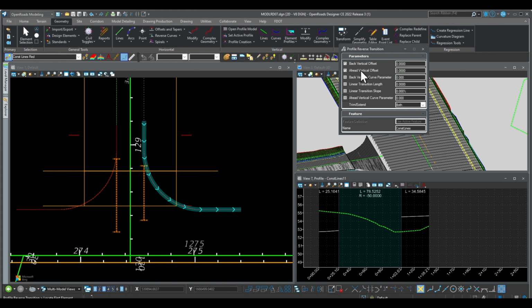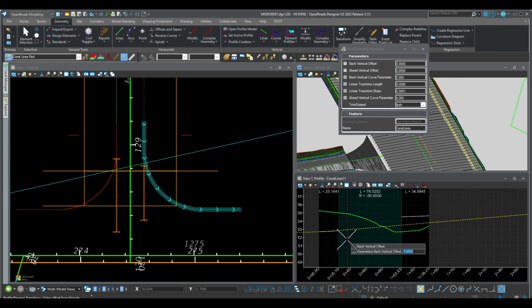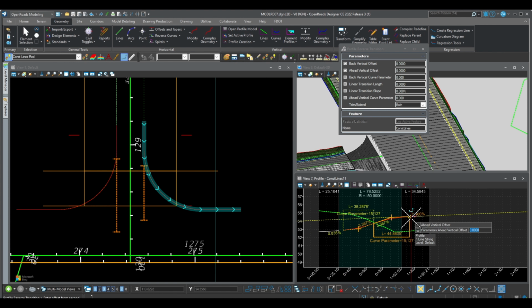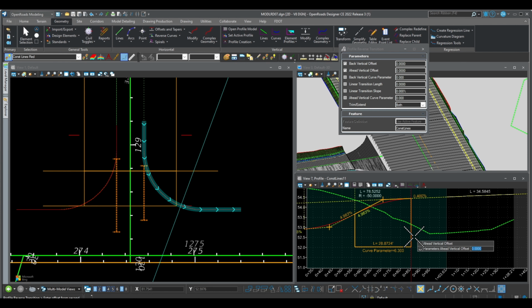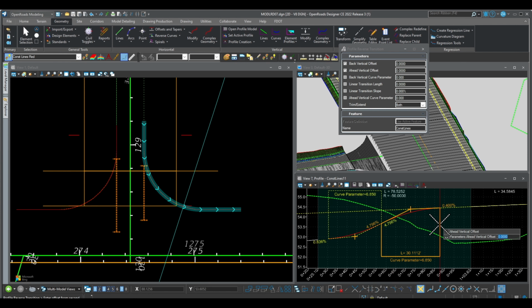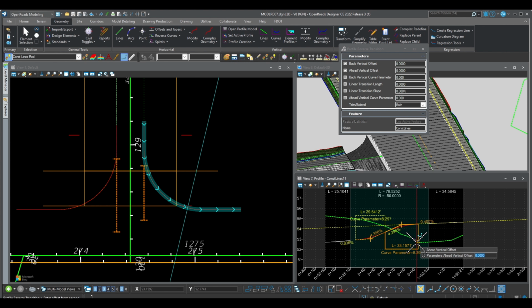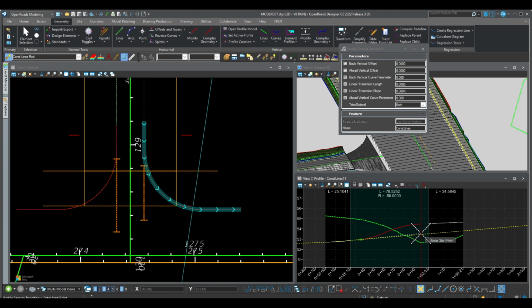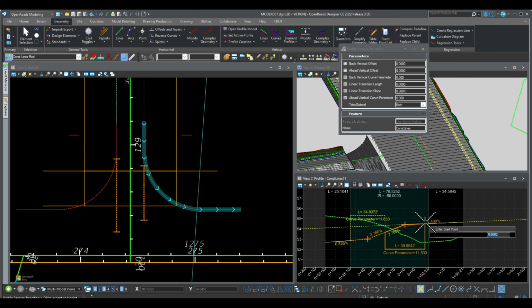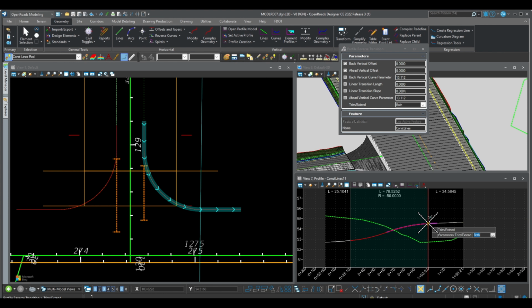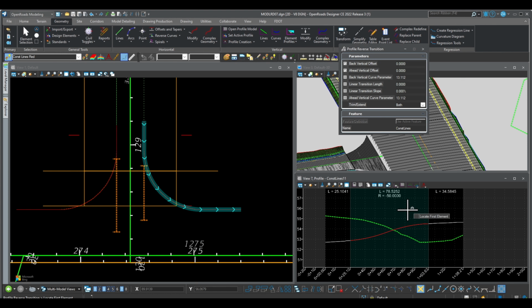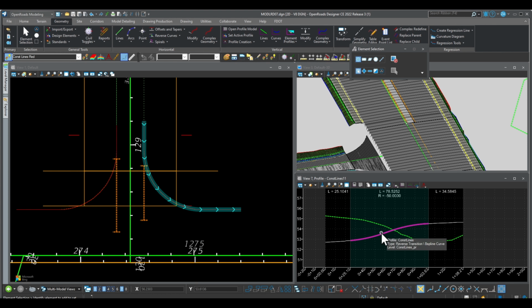So let's select the first element, which is this one. And then just click anywhere, because I already locked it on 0. It's not going to go any vertical. And then let's select the second element. And you see here right now, we have something. It's like it's showing us something, right? So let's just click on 0. And then let's go to start, where I want to start from here, and I want it to end here. And then trim both. And then ta-da! Here we go. Now we have a perfect transition.